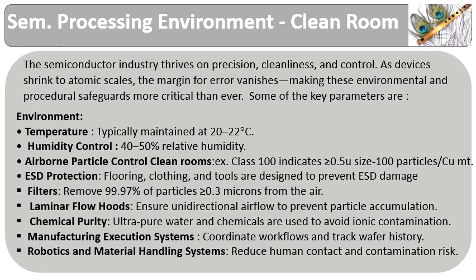Airborne particles present in the processing environment can bridge the interconnect, block deposition or etching, or distort the photomask image transfer. This phenomenon is controlled by filtering predefined size particles. Example: a class 100 cleanroom allows only 100 particles of size less than or equal to 0.5 micrometers per cubic foot.